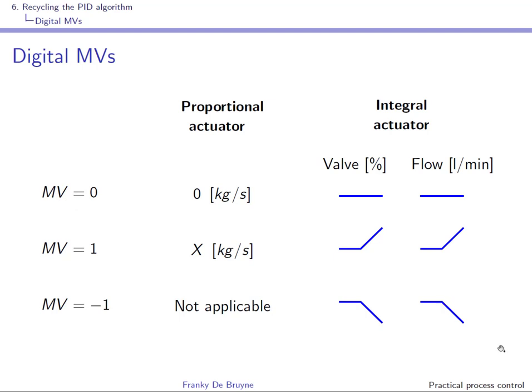In practice you might deviate a little bit from the characteristics that you see here on the slide, because in reality you'll have to take into account the valve characteristics, which might be slightly non-linear, and you might have to take into account pressure variations in the line.